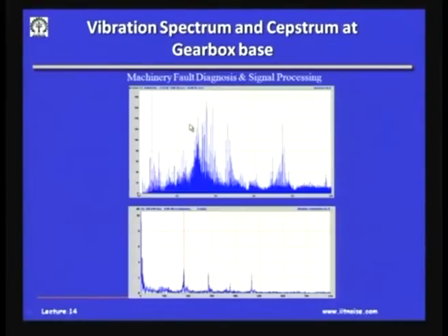But the same spectrum converted to cepstrum, you will see the group of sidebands coming up, Q frequencies clustered, sidebands clustered into their families, and whichever Q frequency has the highest amplitude has a strong presence in that signal, and that is how cepstrum helps us identify the important frequencies in a spectrum. Okay.